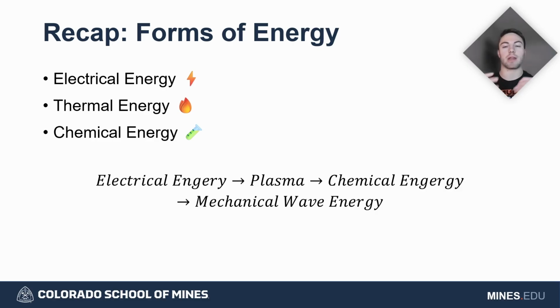There's nothing to bring an explosion or a combustion out until we have added in that energy from the plasma, which then sets off the chain reaction of fire propagating down that tube. So the way that this system works, you have your electrical energy coming from the little igniter, the spark, the voltage generator, which turns into a plasma between the 2 electrodes. And that turns into chemical energy and thermal energy as it is released down the pipe.